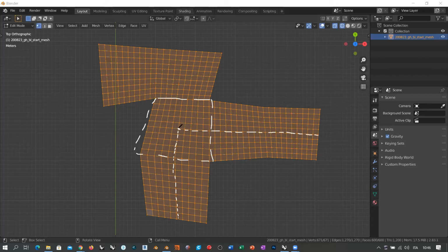And then if I run through this edge, I cannot reach the opposite edge, because else I would have some incomplete sections in my mesh. And so in this case, I prefer to turn right this way and get to this point. Now, think about this in terms of macro loops. So consider like if this was just one polygon, this was just one polygon, and so on.